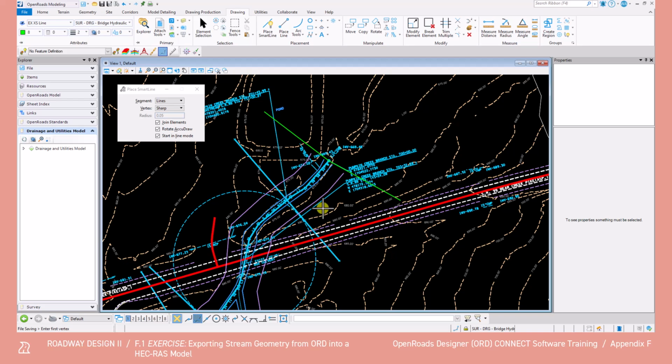And for the remaining cross-section lines, go ahead and first trace the 4 provided in the survey reference file. Like the downstream cross-section line, trace the northwest to southeast direction. I recommend to draw at least 2 cross-section lines on both the downstream and upstream sides of culverts.